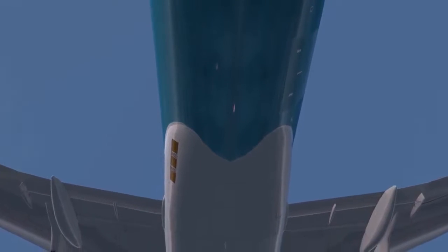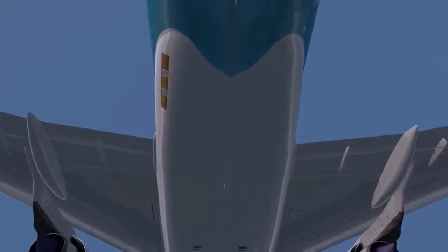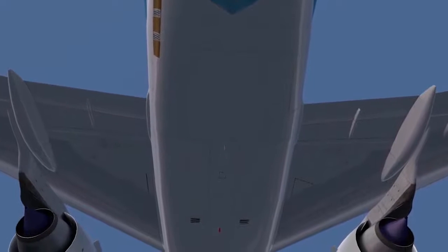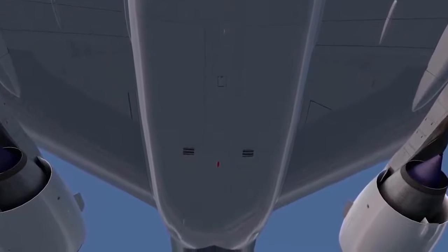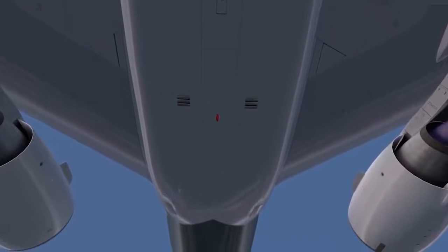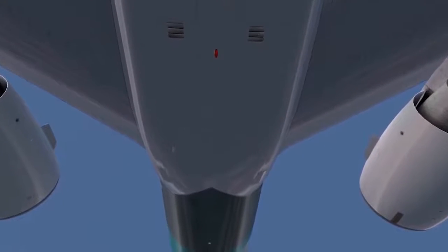The discharge of air is sequenced so that about 20% of air is bled from the forward outflow valve and the remaining 80% from the aft valve. This distribution improves cabin ventilation and smoke removal. In case of a single valve failure, the remaining valve can adequately maintain cabin altitude and full ventilation rates.